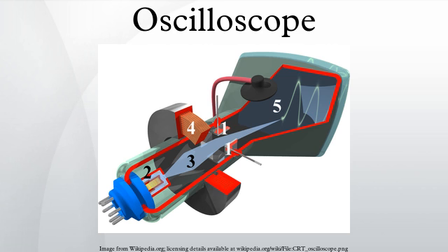These cursors are more accurate than visual estimates referring to graticule lines. Better quality general-purpose oscilloscopes include a calibration signal for setting up the compensation of test probes. This is a 1 kHz square wave signal of a definite peak-to-peak voltage available at a test terminal on the front panel. Some better oscilloscopes also have a squared-off loop for checking and adjusting current probes.